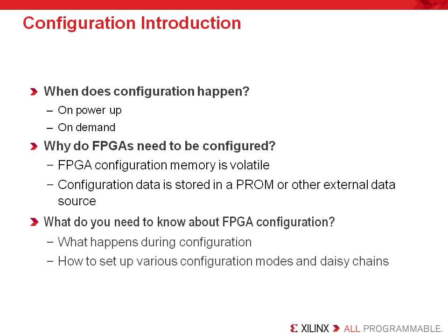To build your system, you'll have to understand the basic configuration process and how to set up various configuration modes and daisy chains. But before you can get to that point, you will need to understand the advantages and disadvantages of each configuration mode so you can choose the appropriate one for your system. You may also need to gain some knowledge of how a series of FPGAs can be daisy-chained to use a single memory source, just in case your system requires multiple FPGAs.